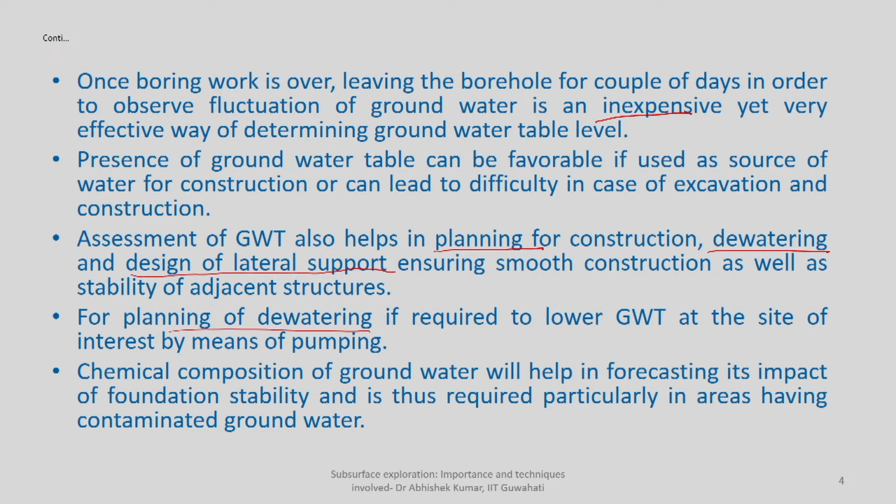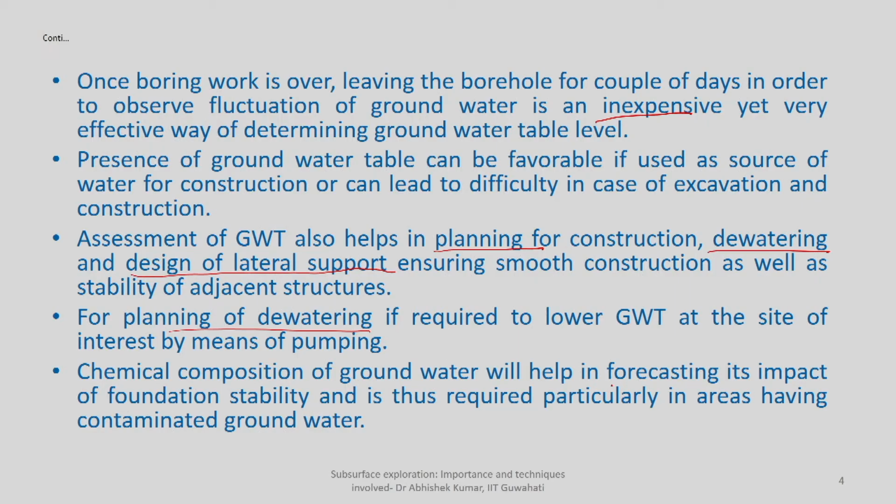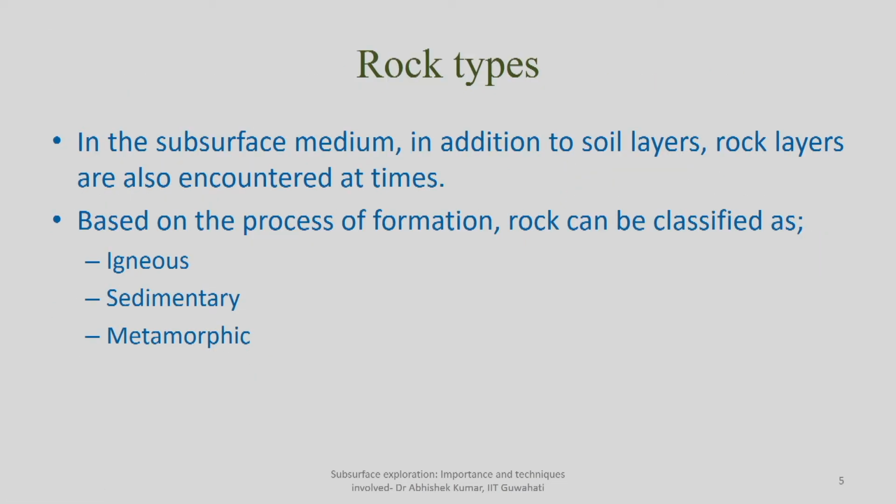So, what is the effect of that contaminated groundwater on the soil, or maybe on the foundation material also? If you know the chemical composition of the groundwater, that will help you in understanding or forecasting what will be its impact on foundation stability, particularly in areas where contaminated groundwater is present. So, once you know those things in advance, you can take suitable measures. So, this was about the groundwater table.